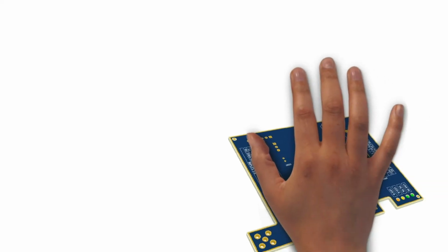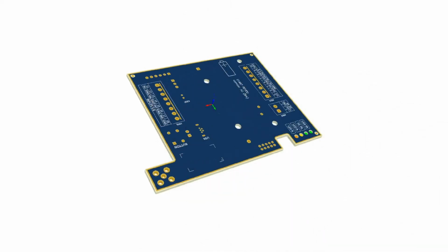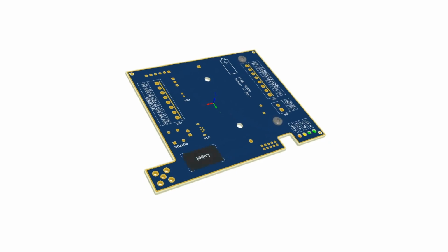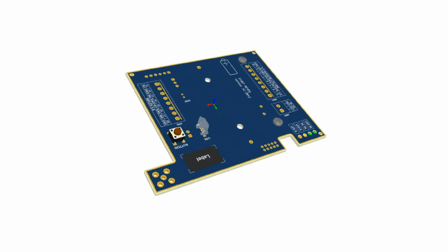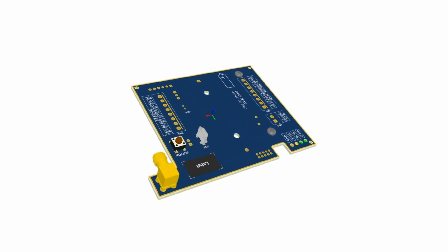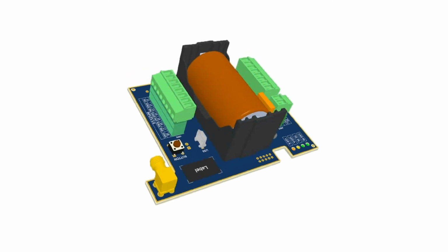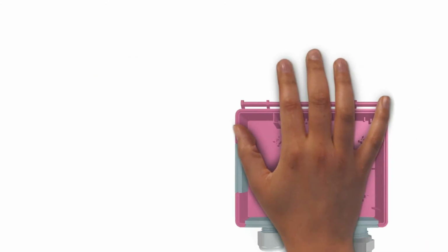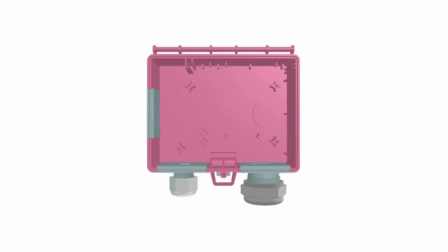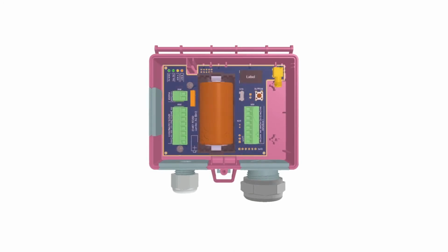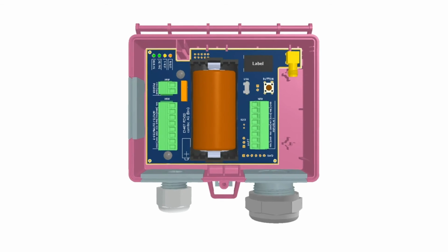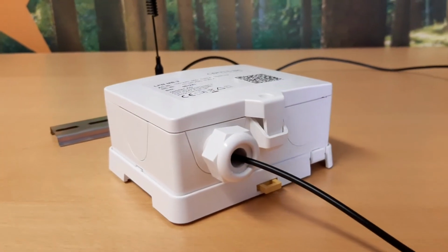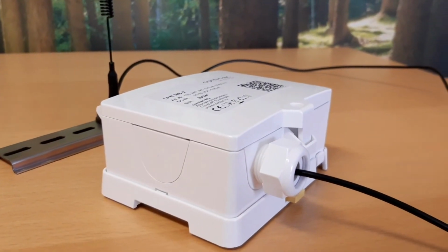By taking all these recommendations into account, you can see that we developed a device with a specific housing, and you can see the PCB form turned around specifically so that it fits on the housing. So we used space as much as we can. We added the groundings on the antenna, and we have a specific boost selected for our device, so we have the best energy consumption we can have. All of these elements build at the end a perfect product that fits these perfect conditions and allows us to reduce the cost of ownership massively.